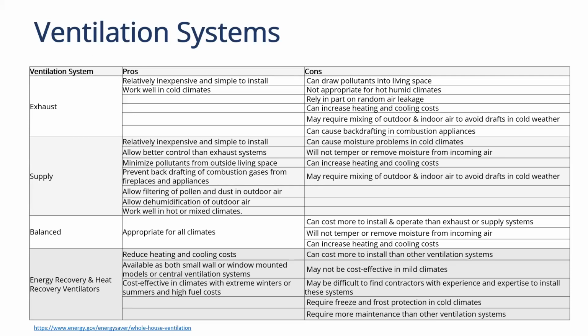That gives you the ability to balance the system and also recover the heat and the humidity from the air and exchange it in the apartment, so that you're not just providing untempered humid air into the building and then having the air conditioning unit have to either cool down or dehumidify that air. You've got some benefit with the energy recovery ventilator where you're tempering that air and providing more comfortable air to the tenants.